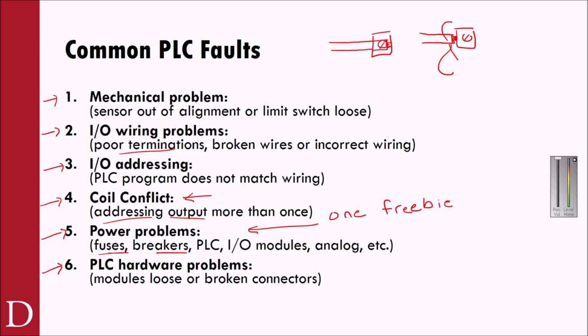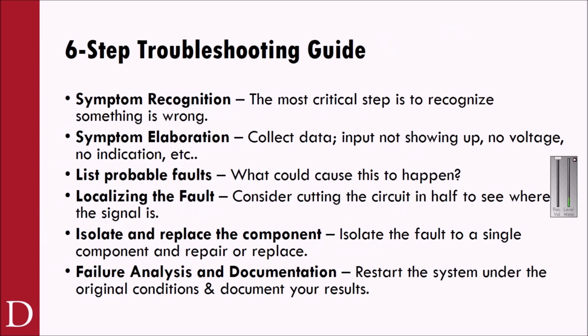PLC hardware problems, again, more likely if machines are being moved, or if machines are first being installed, or the machine's being upgraded. Modules may come loose from the chassis, you may break a connector, but not in typical operation are you going to have these PLC hardware problems.